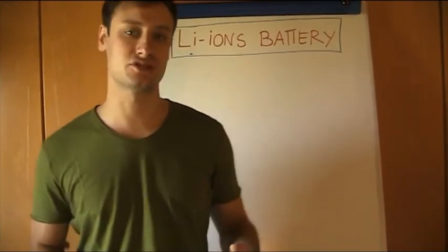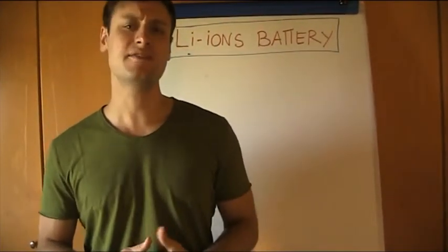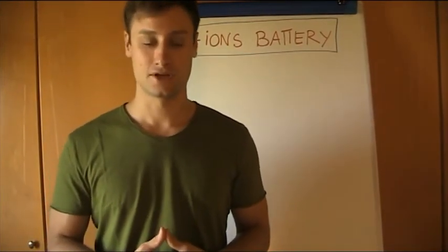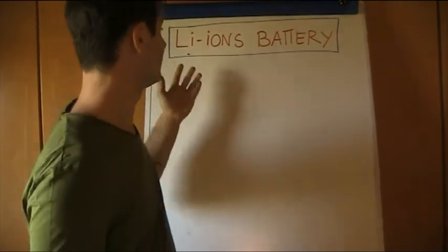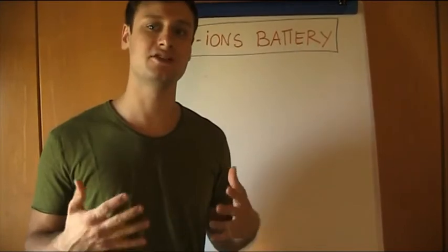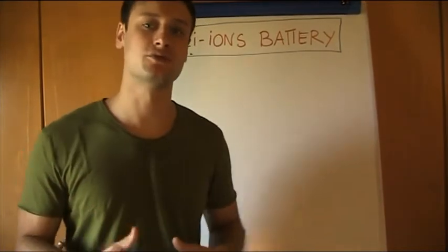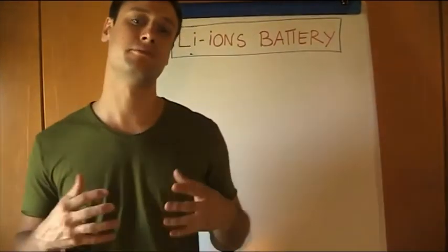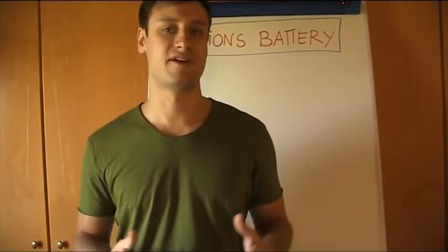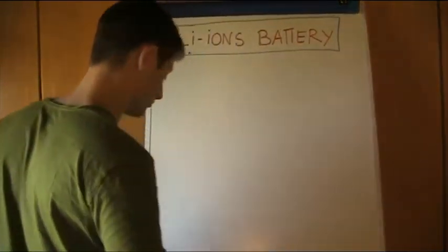And this is due to the extremely interesting output voltage that these batteries can provide, and even the quite high energy densities and long life. So basically, if we want to describe lithium-ion batteries, we need to say that this battery is based on the intercalation process of lithium cations. In order to understand the working principle and the main positive and negative aspects, we need to start from the galvanic chain and the real structure of this battery. So the cell is composed in this way.